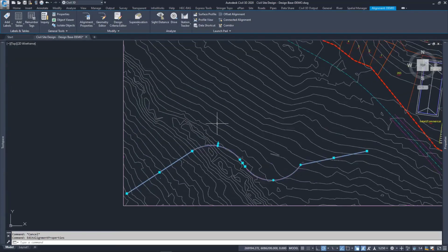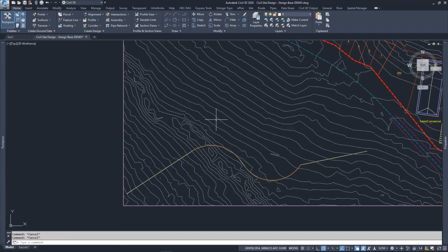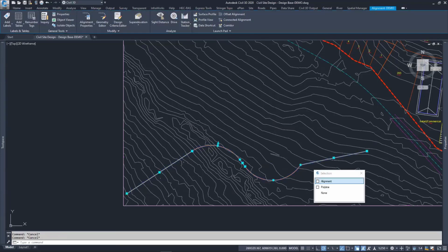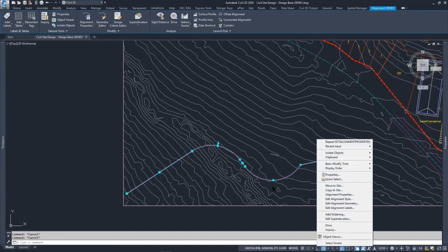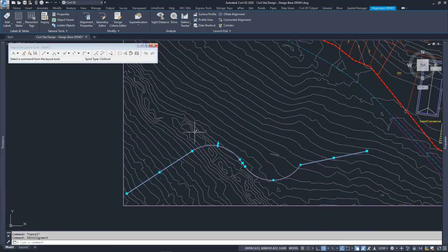We've got a question, a privately asked question, in respect of if you get the alignment direction wrong the first time round. Yep, so you can come into your alignment and go into the geometry editor and reverse the direction.